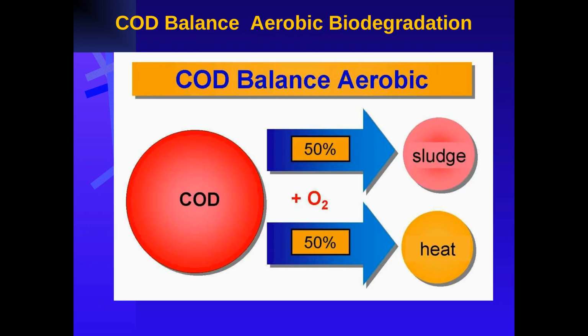In contrast, anaerobic treatment offers numerous advantages. It consumes very little energy and, in fact, produces energy in the form of biogas. The low sludge production minimizes disposal costs, and the process is well suited for treating high-strength wastewater with high organic loads. Anaerobic systems are also more compact, requiring less land area.